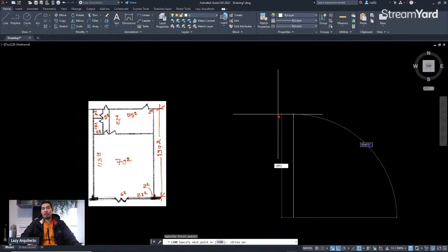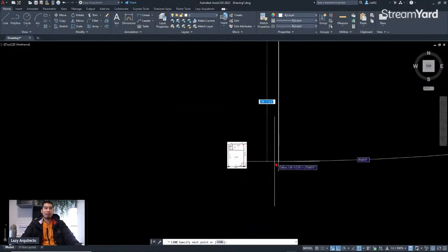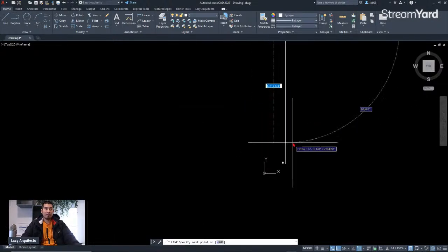At this point, I don't need to use the inches symbol, because AutoCAD already knows that after the feet, 2 would be inches, because we specified the correct units for our drawing. So we are good in this specific example. Once you typed your distance or your number, simply press enter, and you'll have your first line over here.